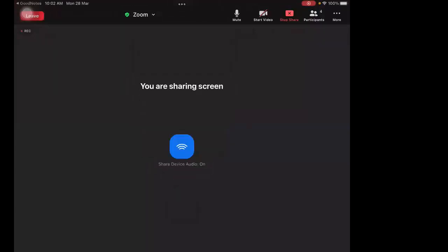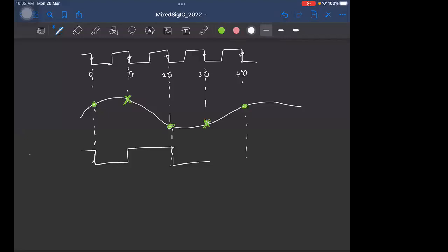For the first ADC, that is sampling at 0, 2TS, and 4TS, the clock must look something like this, right? The falling edges again define the sampling instant. And for the second ADC, the clock will just be a phase shifted version of this. So here these define the sampling instance, and this is how it works.